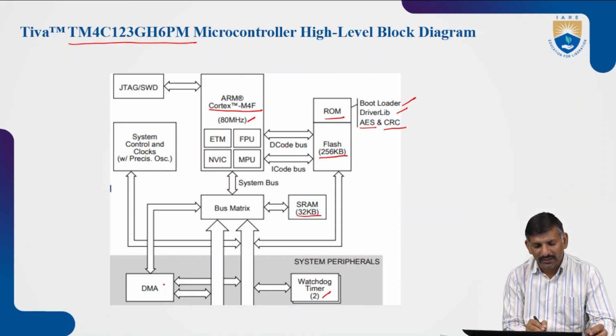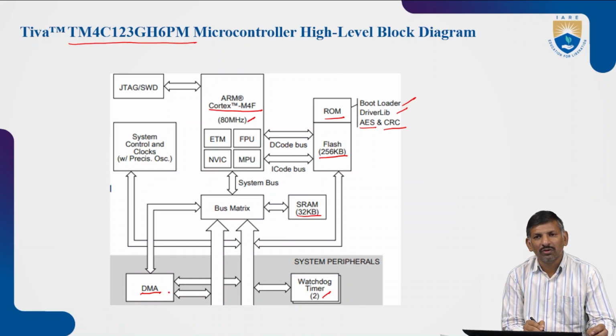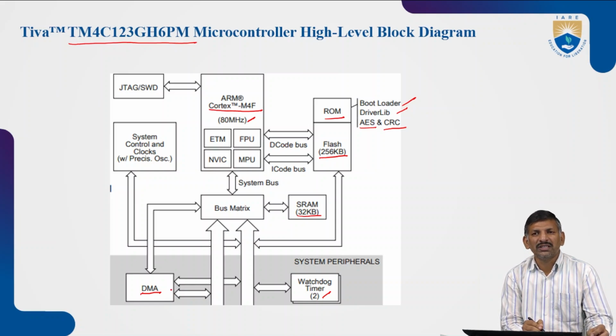Okay. Next, it contains an on-chip DMA controller, direct memory access controller. So, without CPU interaction, it will perform the read and write operations with the external memory devices to speed up the operation and for efficiently utilizing the central processing unit.